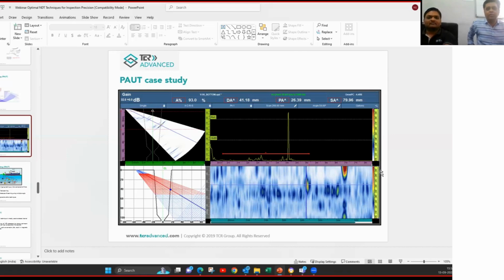Yeah, basically, acoustic emission testing is a technique which has certain advantages over the conventional technique. Number one is that it can inspect the entire equipment in one go. What I mean by that is that the equipment as a whole contains parent metal and weld joints.